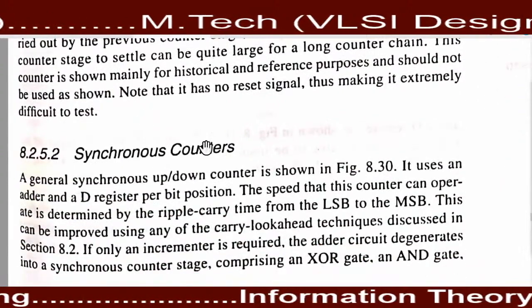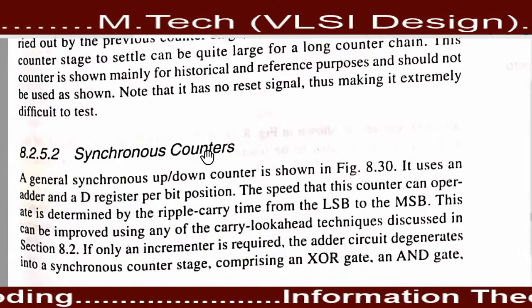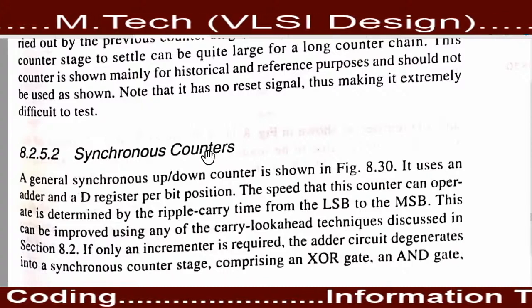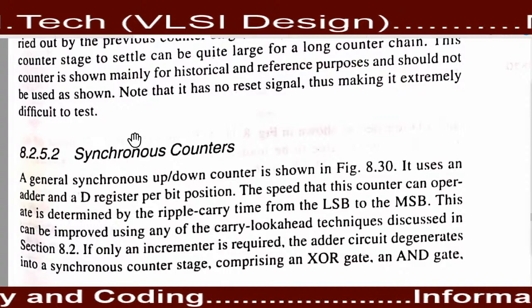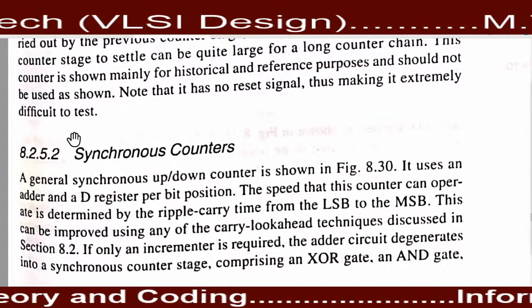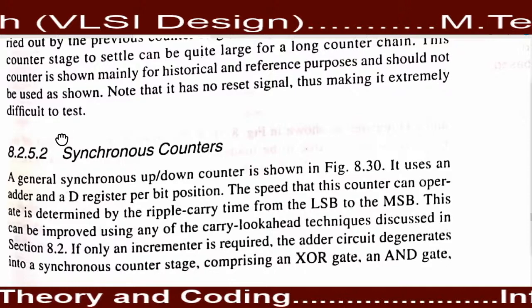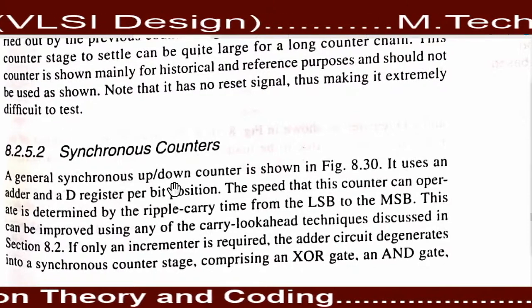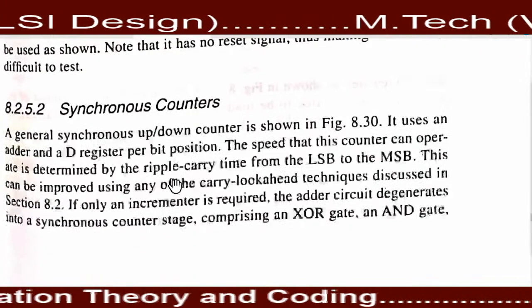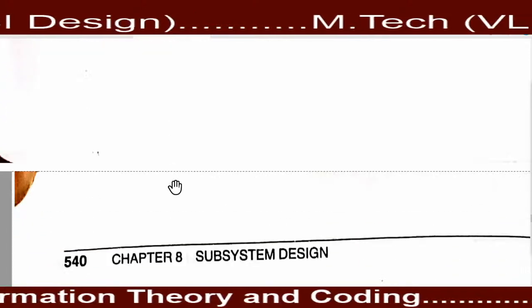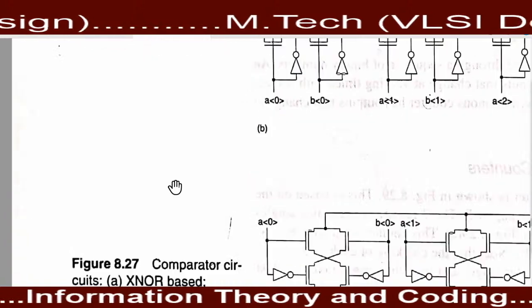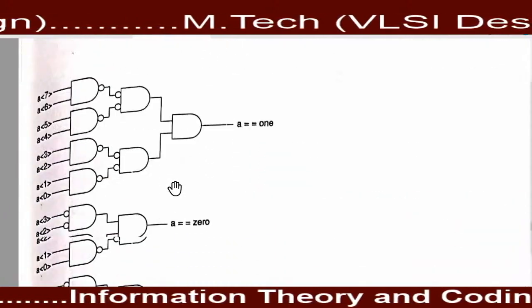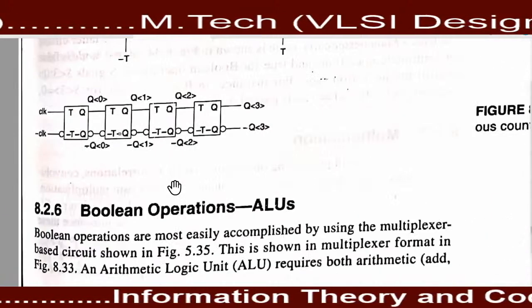Now to speed up the process, if all flip-flops get the clock pulse in the same time interval, the speed will be higher, and this feature exists in the synchronous counter. That's why we can say the speed of the synchronous counter is much higher compared to the asynchronous counter.